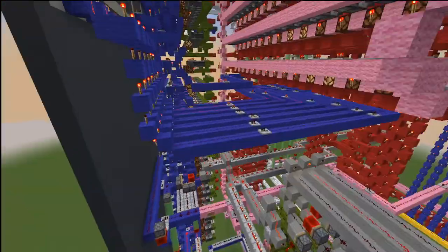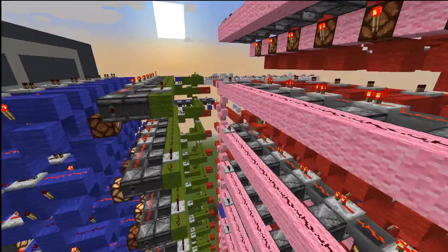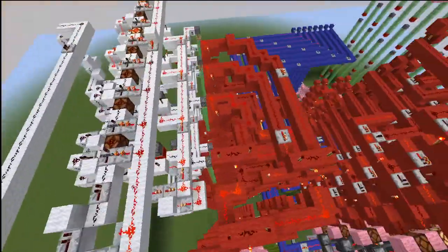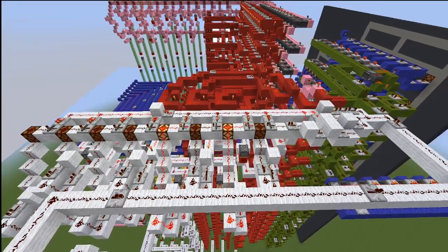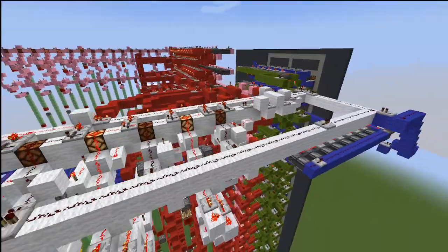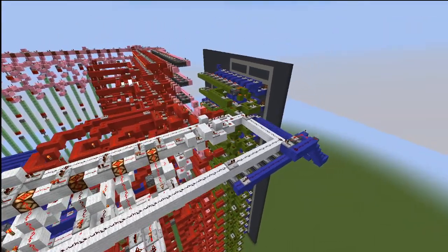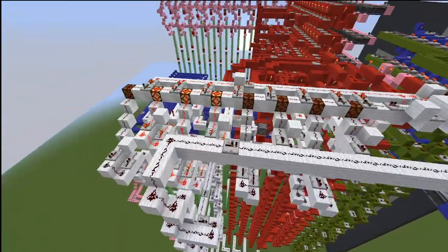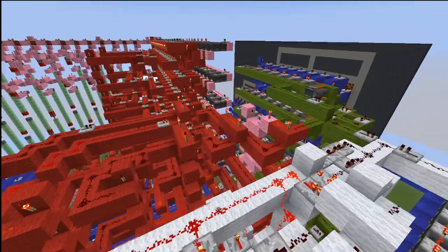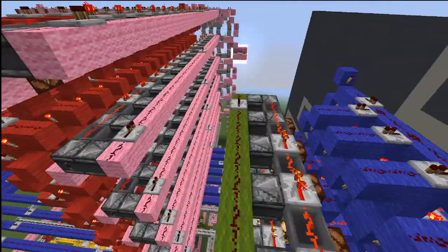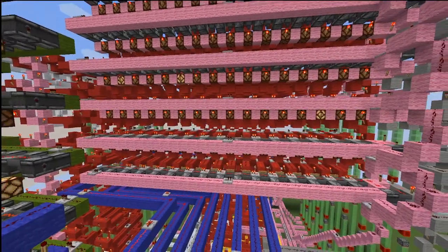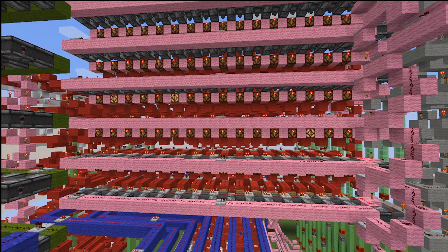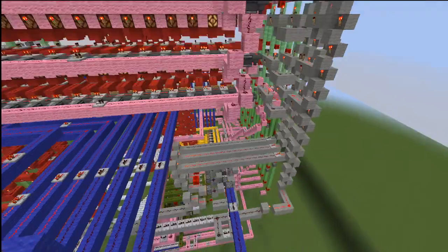So here we are now starting the macro instruction for halt. It's going to bring a 10 from the program counter up here. And there it is, that's binary 10. We've got 8 plus 2 is 10. And it's got to select PROM line 10, and it just did, and that's the halt command there. So now we can see the instruction register update to include the halt instruction. And there it all goes, it updated.